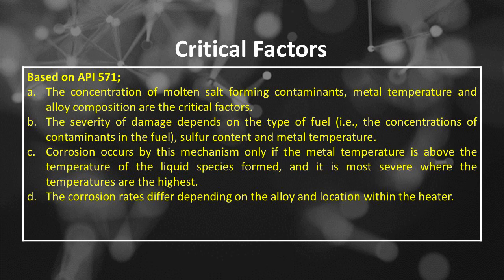Corrosion occurs by this mechanism only if the metal temperature is above the temperature of the liquid species formed, and it is most severe where the temperatures are the highest. The corrosion rates differ depending on the alloy and location within the heater.